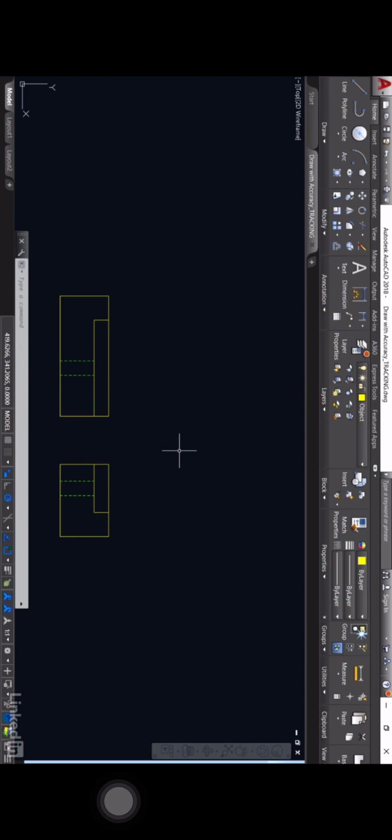So now we're going to start drawing some lines. We go up to the draw panel on the home tab, click on the line command, and I'm going to hover over this point here. I just hover over it, I don't click on it, and I drag vertically upwards and it'll say extension. That means my extension snap is on. If you don't get that, go to your object snaps and switch your extension snap on. I'm going to type in 50 there and enter, and you can see that my line now starts 50 above that point.